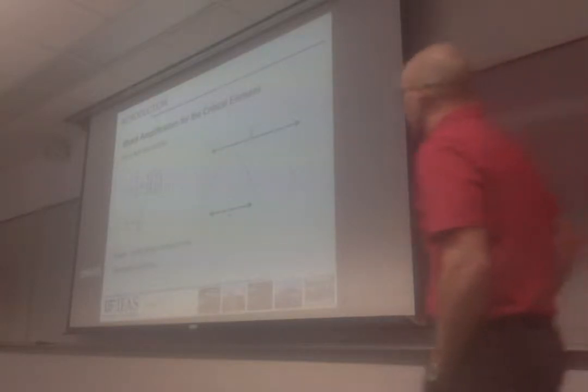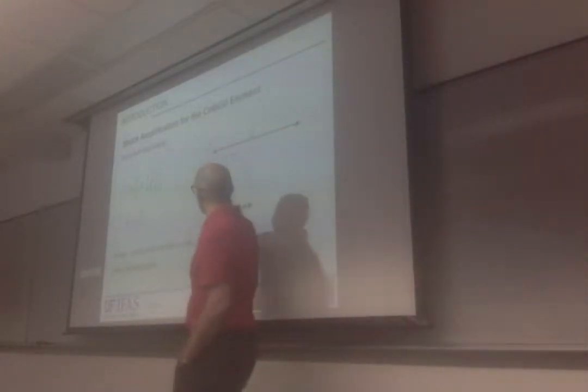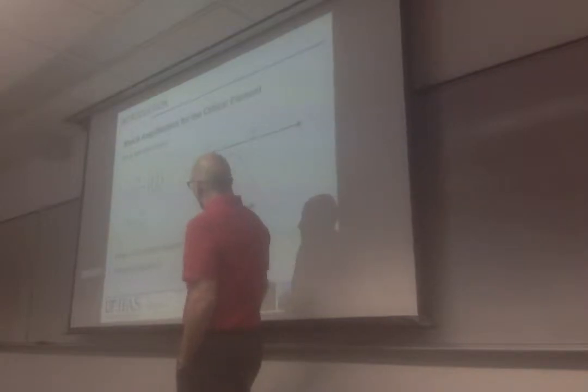So we don't have an equation to calculate the amplification factor. What we do have is that table that links the natural frequency to the impact frequency or input frequency. And that input frequency is related to the duration of the shock. So this is, I think, pretty well explained here.